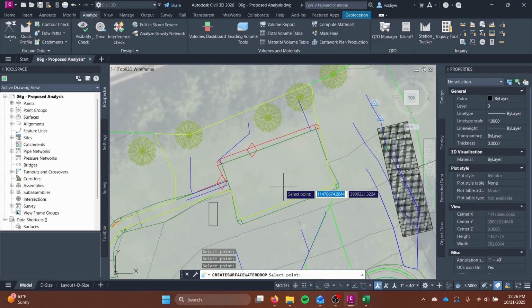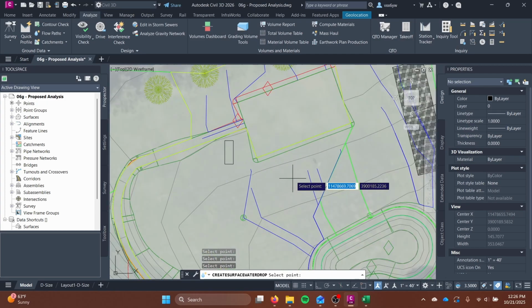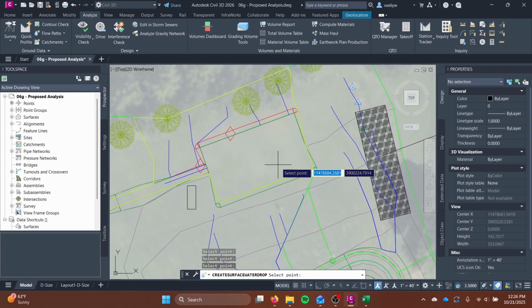If it's north and south, for example, we know this pad is 40 by 70 feet. I might take half of that area and include it in the catchment up here, and take half of that area and include it in the catchment down here. And it's also an entirely impermeable surface, so I might do a runoff coefficient of 1 because no water is going through the roof. If the water's going through the roof, that'd be really bad.